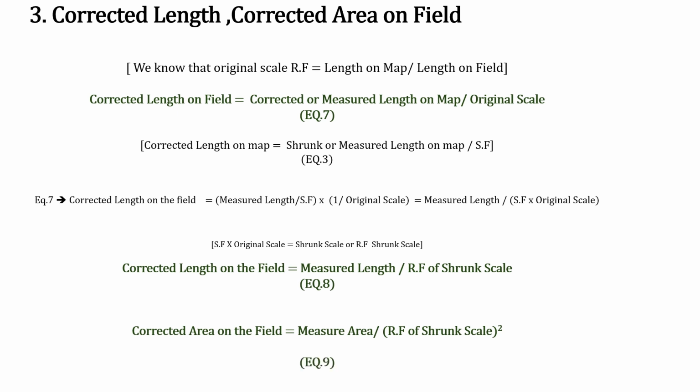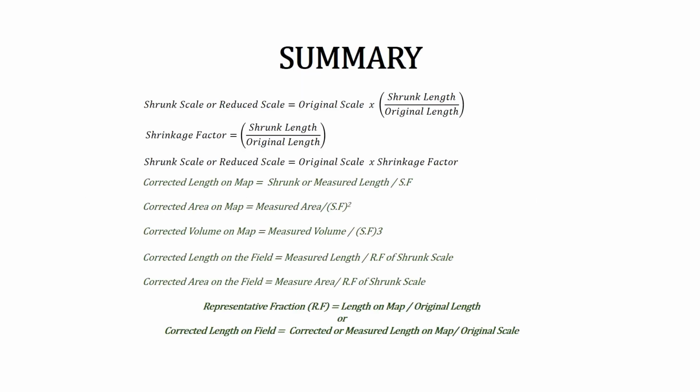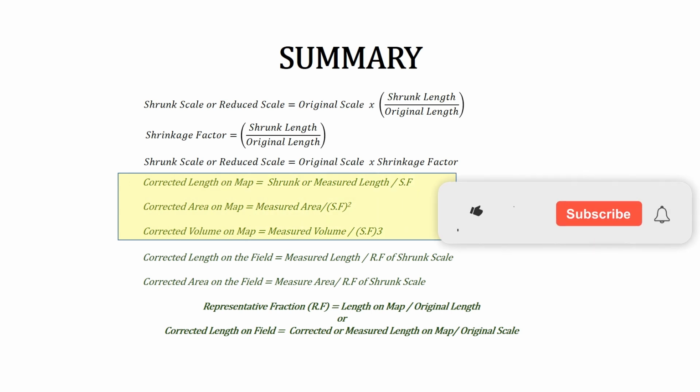This is a summary of all the equations related to shrunk scale in surveying. All the equations for determining corrected length in the map employ shrinkage factor, while those for corrected length on the field employ shrunk scale.